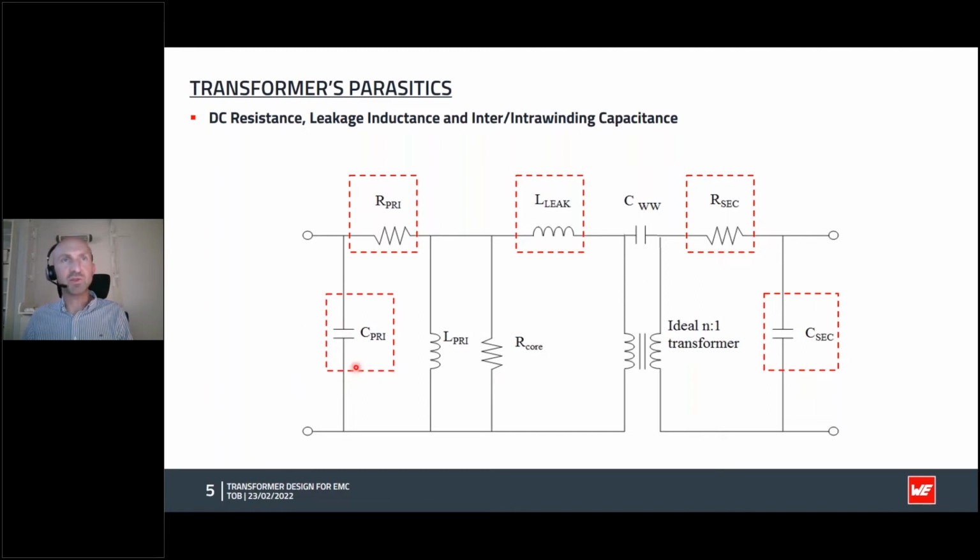And that can cause some issues, particularly on turn on. We get a spike caused by this capacitance, and also the capacitance, say, in the MOSFET switch, and that causes a spike. And again, everywhere you have a spike, you'll have some ringing that follows on from parasitic capacitances and inductances in the circuit, and we have the same capacitance then on the secondary side, intra-winding capacitance.